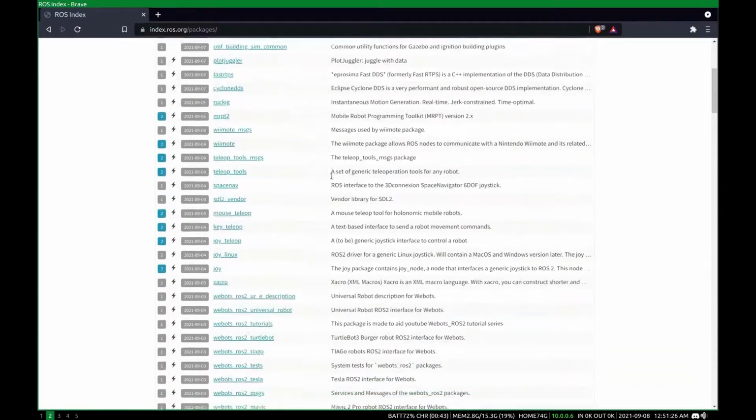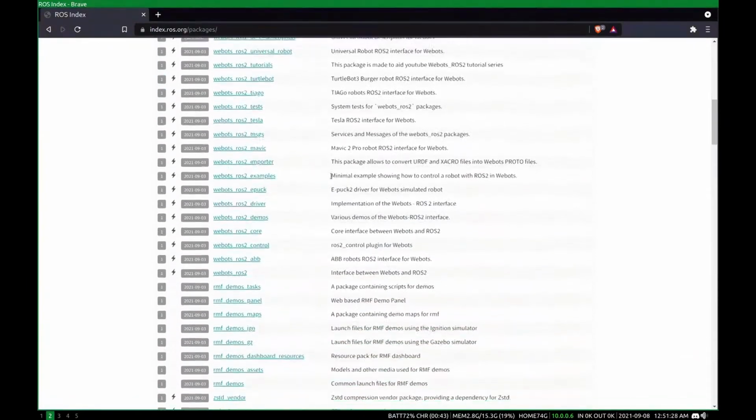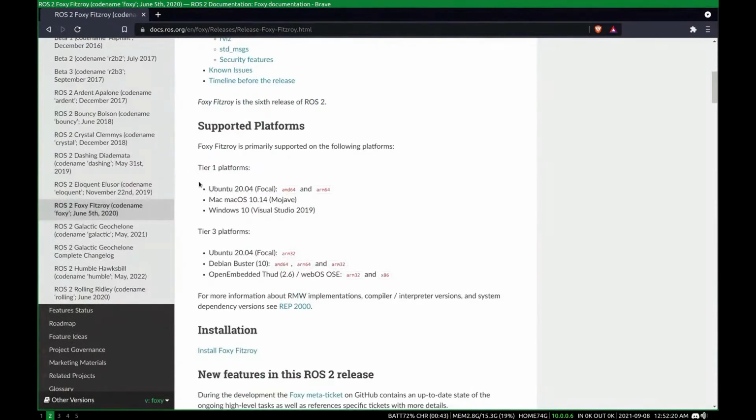The standard DDS framework for robotics is ROS, the Robot Operating System. ROS offered powerful multi-drone control and communication features, and a huge ecosystem of libraries in support. So why didn't we use it? We discounted ROS fairly early on because we found it to be too opinionated. A big pain point was ROS's tying of distributions to specific Ubuntu versions, which we found to be too limiting for our team to develop effectively on.